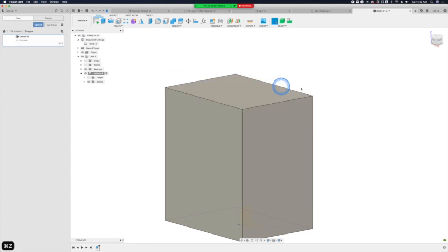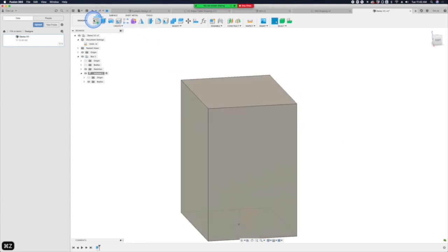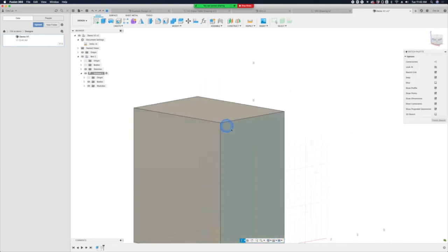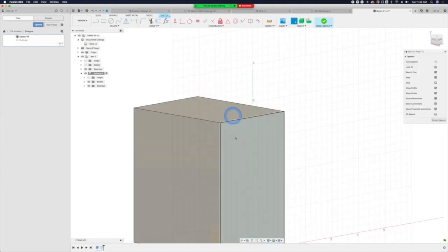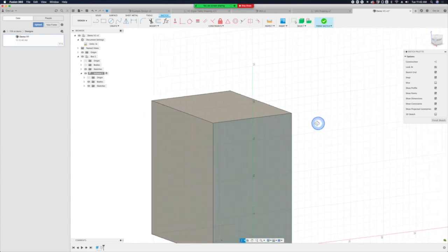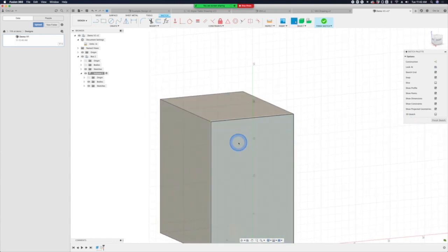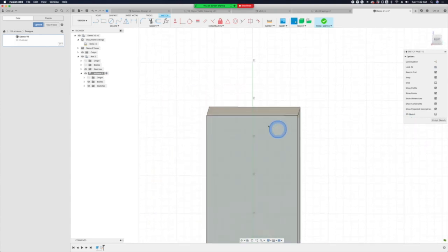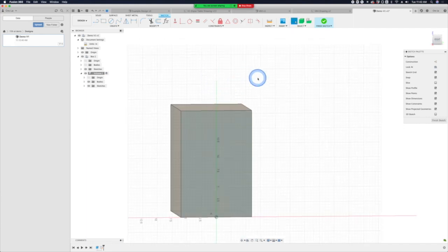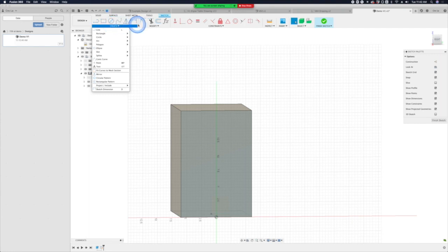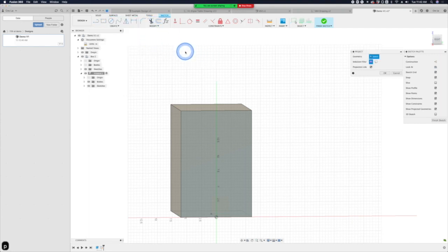I'm going to undo that. All right, so let's just keep it a little simpler. So I just selected a feature. These are all planes that we've created now because we have this volume and space here. Just pick the side. We're on the right side. Now I'm going to hit, well, let's see. I guess P is the only way to get this. I hit shortcut P, and you're projecting geometry.